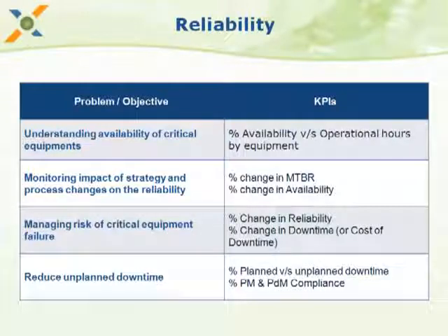So if we are going to calculate some of these factors, then we have to know what the cost of the downtime is. Similarly, we can monitor unplanned downtime, which will help understand how effective our PM and PdM programs are and how compliant we are with these PM and PdM programs.